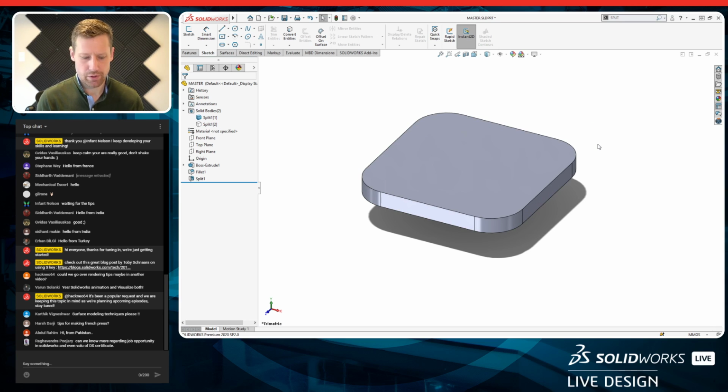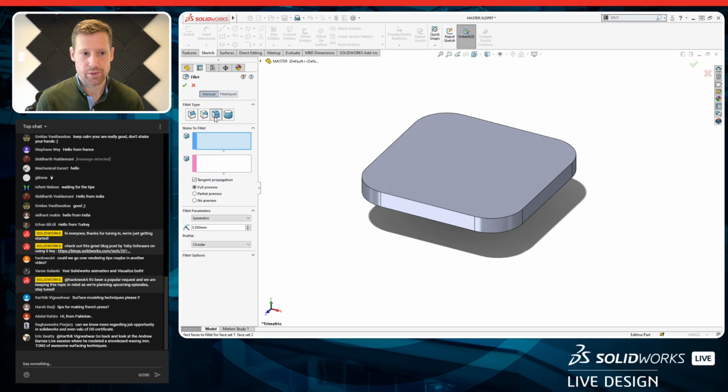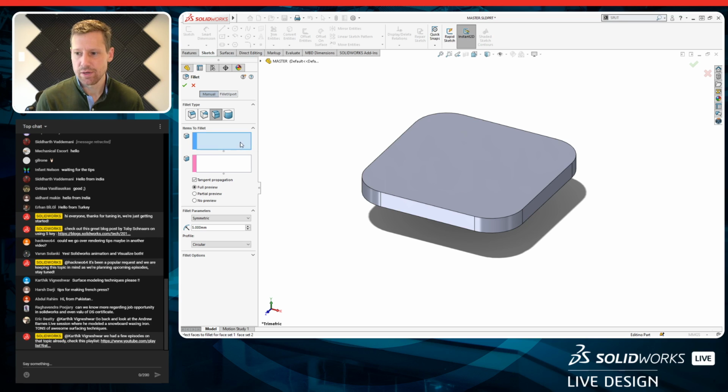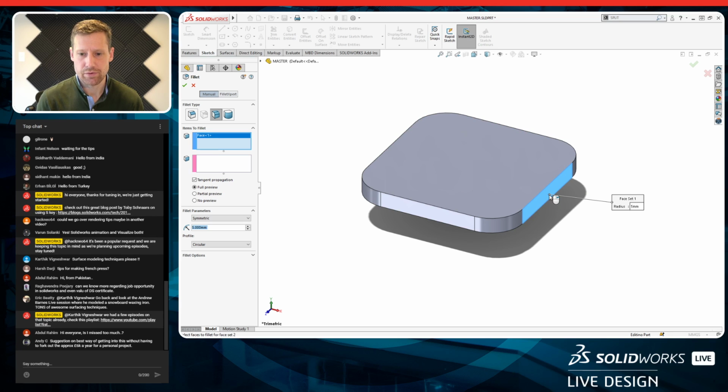And instead, we're going to try for a different method. I'm going to use the same fillet tool, but instead of using just the constant size fillet, we're going to head over here and choose the face fillet. Okay? Now, I'm going to talk about these boxes here real quick. When we see blue in one of these boxes, what that means is that SolidWorks is expecting us to click on something and fill that box. So that's the active one. So I'm going to select one of these faces.